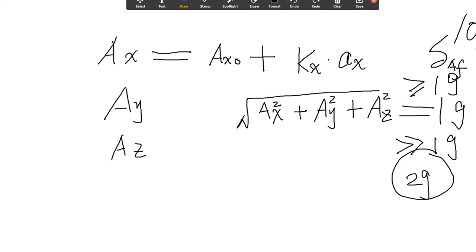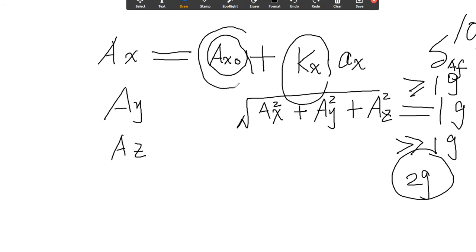So in that case, I think the most important thing is first you need to test whether your system model is right or not. That means, how to test that? For the one I have seen, Lee showed his mobile phone is already well calibrated. That means when you have no acceleration, you only have gravity, so the total square root of the sum is nearly 1. That means the calibration is very good. But sometimes if your accelerometer is not well calibrated, for example you have drift, then this one is not 0, or this one is not 1, and then you need to calibrate. Normally I think all accelerometers currently are well calibrated.